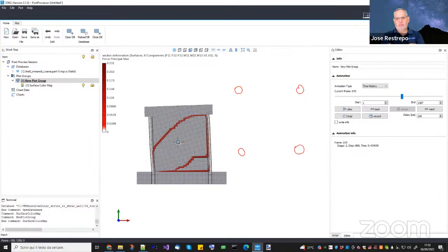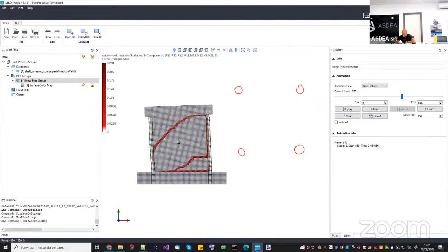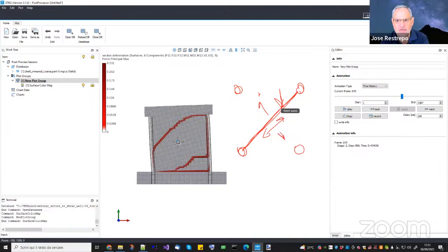What I've seen, for example, is that the diagonal that you see here is actually made of 4 nodes in OpenSees. You have 2 nodes that define the axial component, and then the other 2 nodes, and based on the angle, somehow with them you obtain the transverse deformation, and with this transverse deformation you change the behavior of this one. The constitutive stress-strain relationship in compression, yes.